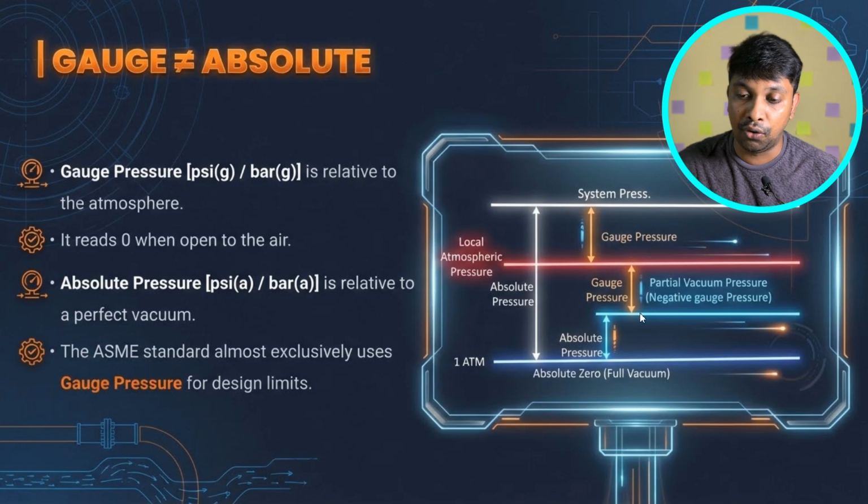Absolute pressure, the full vacuum, partial vacuum, everything comes under external pressure. If there is any external pressure, we will experience this absolute pressure like full vacuum and partial vacuum. Not only in terms of external pressure, but also if there is any pump connected to the vessel, or any steam in, steam out condition, at those times we will use this absolute pressure.